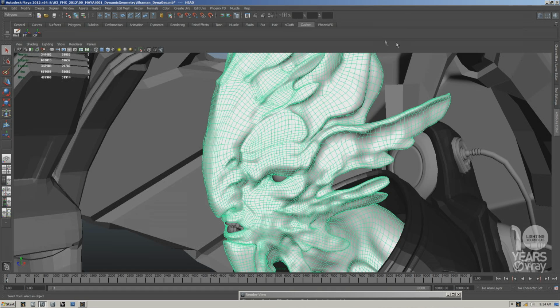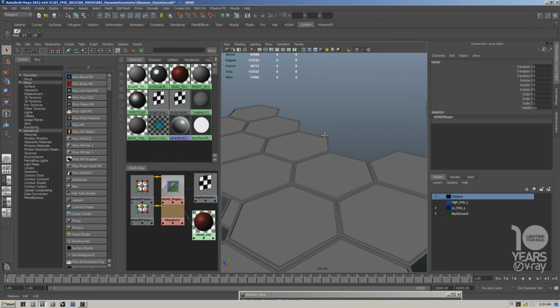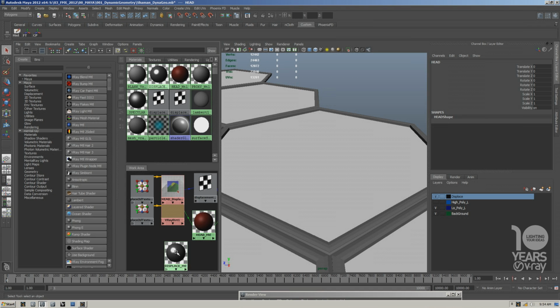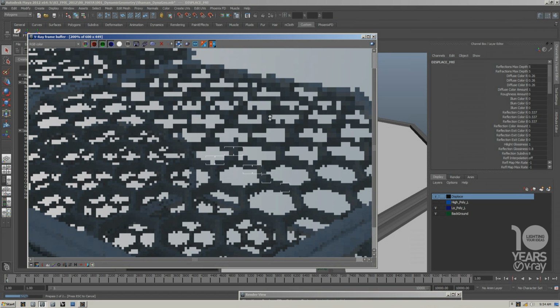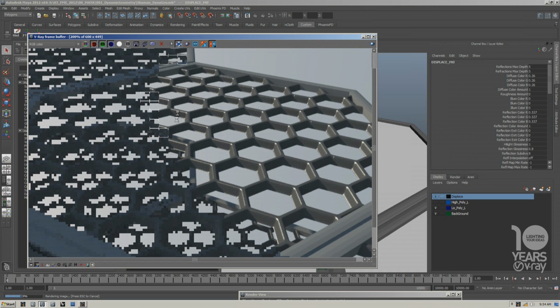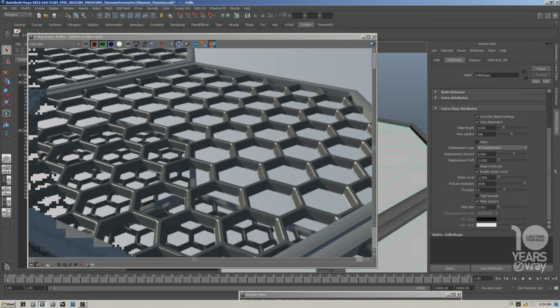Okay, so this is a simple example of the displacement. Let's take a look at another one. So I'll enable a layer and apply material with displacement to this layer. Okay, so if I render, you'll be able to see the displacement that I'm applying to this ground plane. And in fact, there's something else interesting that I have here. You can see that these inner parts of my geometries are missing. And they're missing because I'm using water level at the moment, which is a feature of the V-Ray displacement. The water level allows you to cut out all the geometry that is displaced lower than a specific value. And you can see that right now my water level is set to -2.9, which is exactly the level that I want to be cut out.